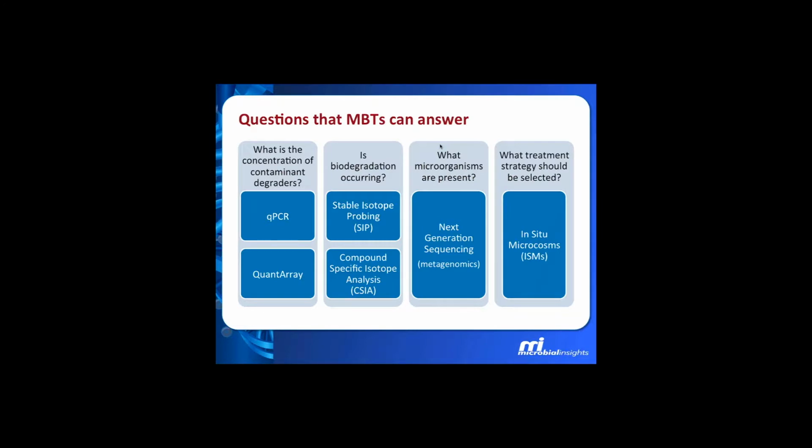Today I want you to think, and if you've heard me present before you've heard me say this a million times, about the question that we want to answer at our site. If we put one of these in situ bioreactors in to get complete reductive dechlorination, we might have questions about the concentration of contaminant degraders that we have. Are we stimulating our Dehalococcoides with this treatment, not only in the treatment well, but also at those down gradient locations?